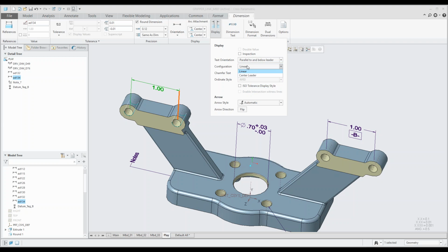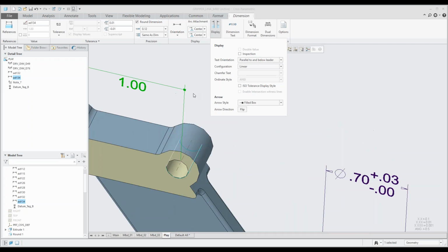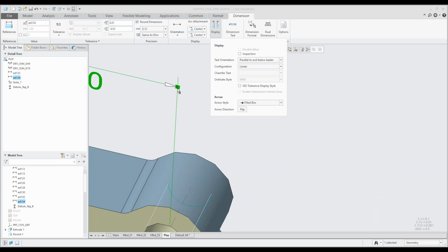So this is a good example of where you will set these settings in the 3D detailed options. So if you set all of that, you'll have your dimensions as you need them. So maybe it's worthwhile spending time and setting all of that up. That's just going to save you time when you start using the model-based definitions stuff in Creo. So you can add your arrow styles as well. Update them immediately as you make your changes, so you can get a good feel for how they will look, and whether it will be clear enough or not.